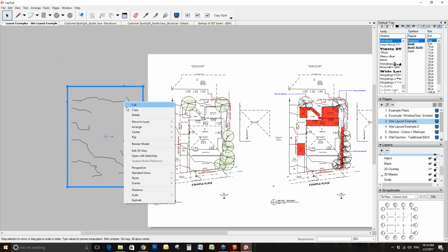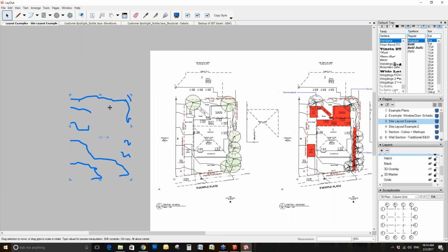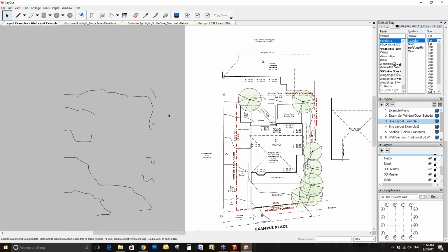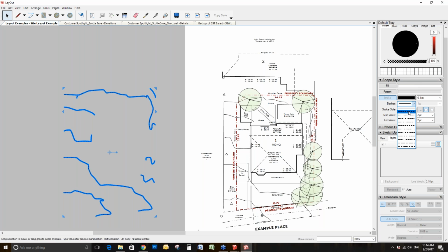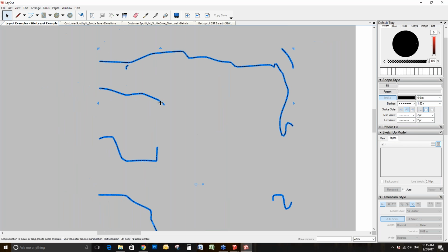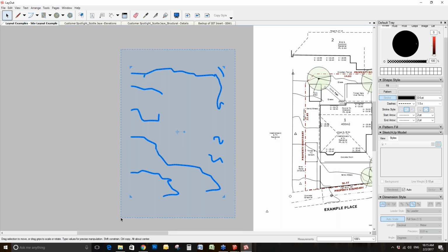I just realized I never actually showed you how to explode. All you need to do is click explode. Once you've pressed explode, you can see that everything's been grouped. So you can just ungroup it, or you can just double click into the group. Now you can select, for example, a whole bunch of your lines. Grab them, and you can say that you want them to be, for example, dashed. You can set the line weight and everything else, however you want it to read, and that's obviously going to update. And then you can simply grab it and group it if you want to.